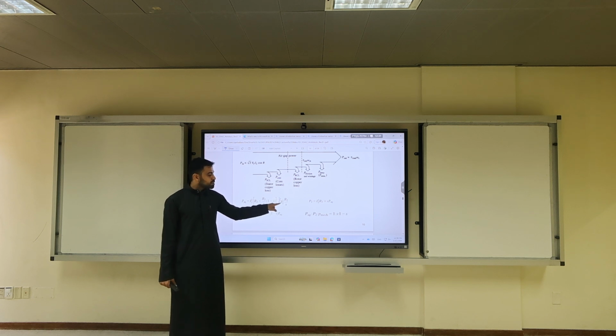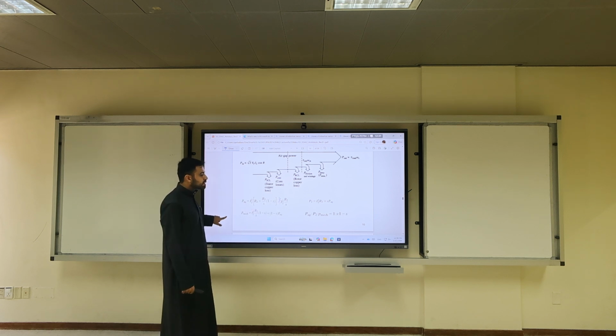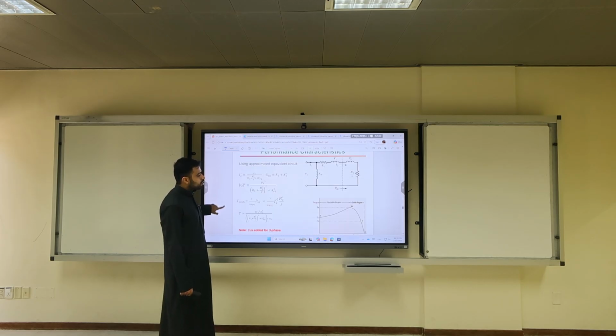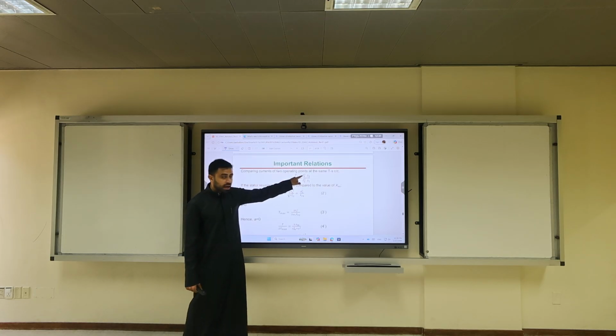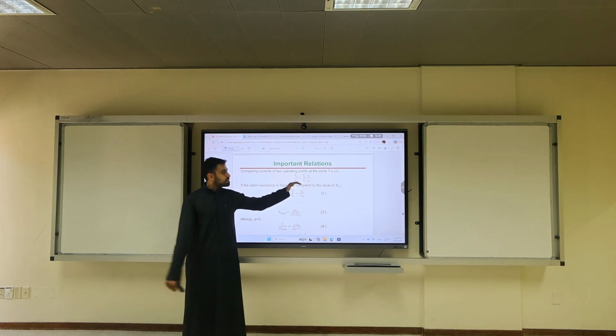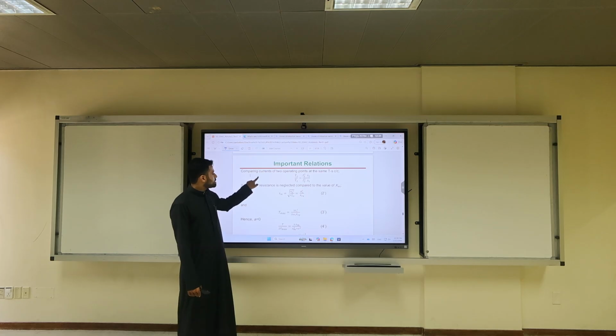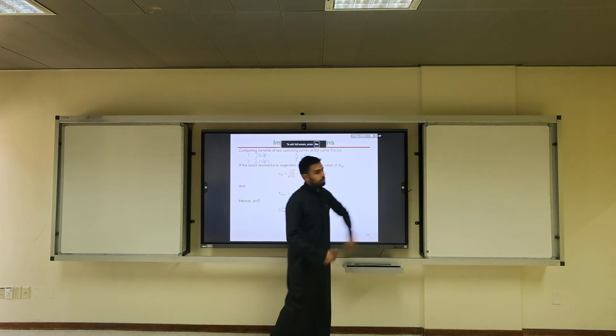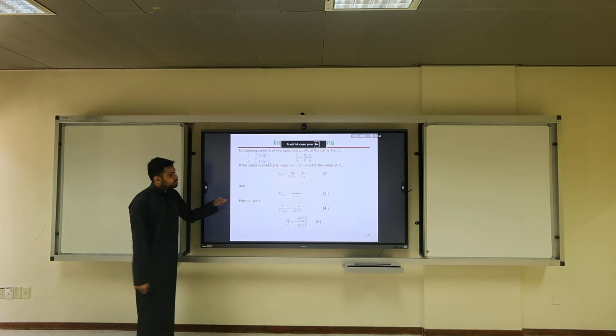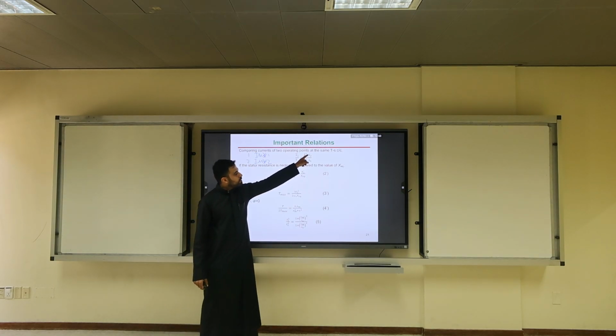Now, I2 is proportional to I1, which is the stator current. So, doing some math, you would note the ratio between the current at machine 1, this one is not rotor or stator, this is machine 1 and machine 2. So 1 is IM number 1, and 2 is for induction machine number 2. So I'm dividing the two ratios by each other. Clear? So if I divide the currents, I need to have S2 over S1.